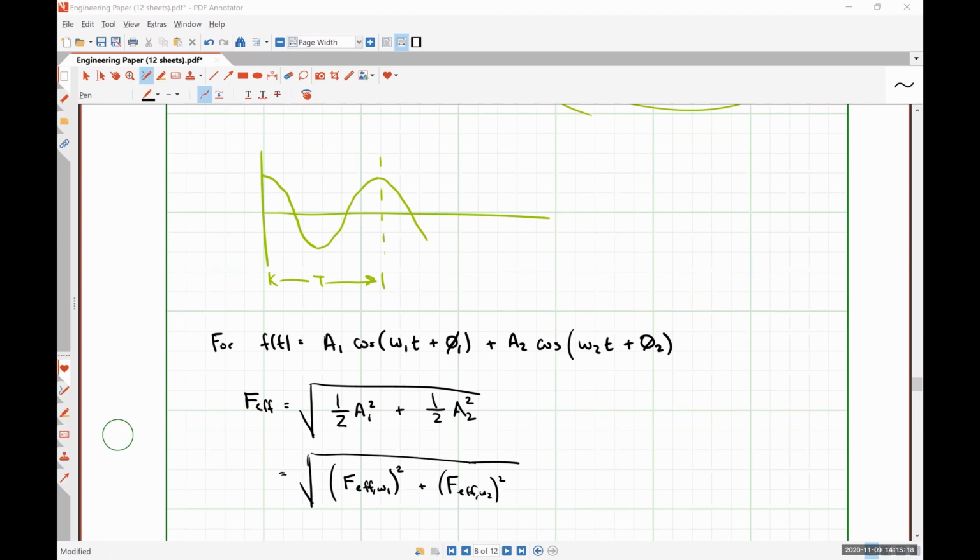So that means you're going to have to convert that to its effective value simply by dividing the magnitude by the square root of 2 before you're able to answer parts D and E. So A and B do not want the RMS values, D and E require the use of RMS values.